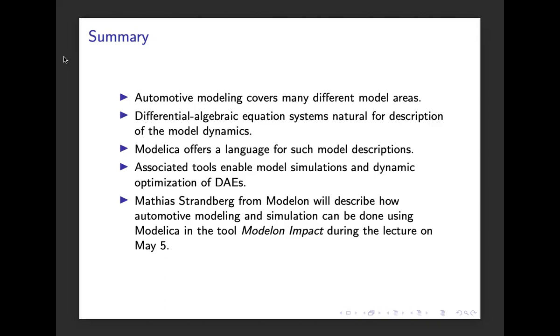Exactly. Which sort of interfaces do you think there are between this higher level of control, I would say maybe autonomy, using a buzzword, and these lower levels of modeling? Yeah, depending on what requirements we have on the high-level modeling, it might not be necessary to have the full detailed level of, say, the tire dynamics or the powertrain dynamics.